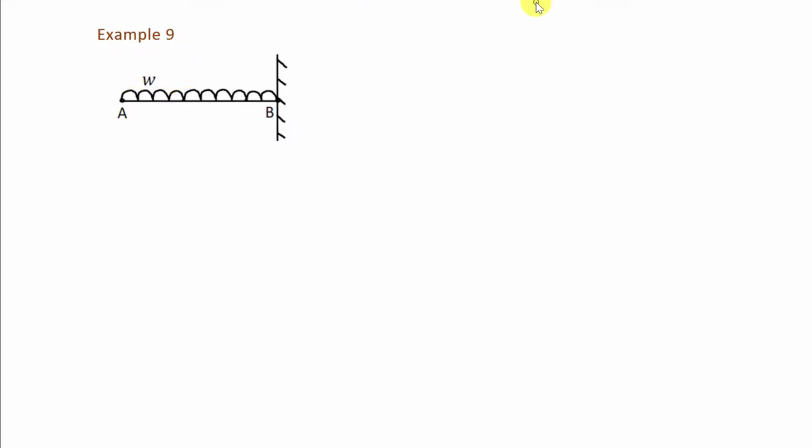So here first of all we will take interval, that is 0 less than or equal to x less than or equal to L. Now in this interval we want to find out value of shear force and bending moment. So for that we will take a section which is at the distance of x from the end A. Now how to find out shear force at this section?